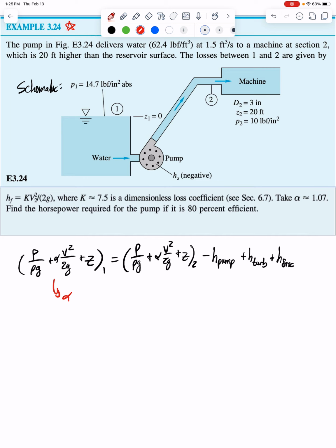The reason it exists is that in pipe flow, you're going to have some kind of velocity profile, a velocity distribution of the fluid as it goes through the pipe, whether it be fully developed as a parabolic flow through your pipe, or maybe it's currently developing and looks something more like this. The alpha term is meant to correct for that and get the mean velocity going through your pipe, because we can't really assume 1D inlet and outlet all the time. That's why the alpha term exists.